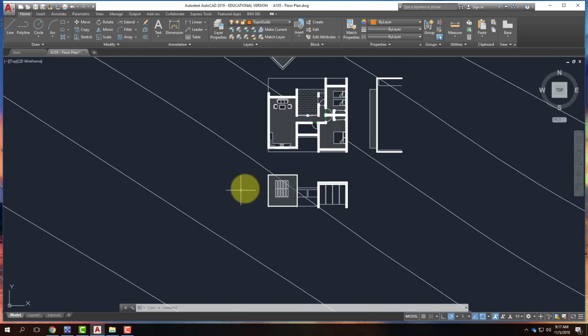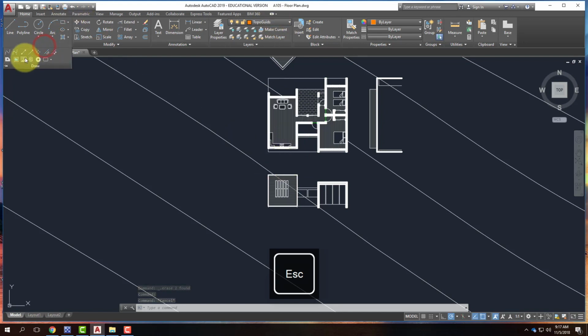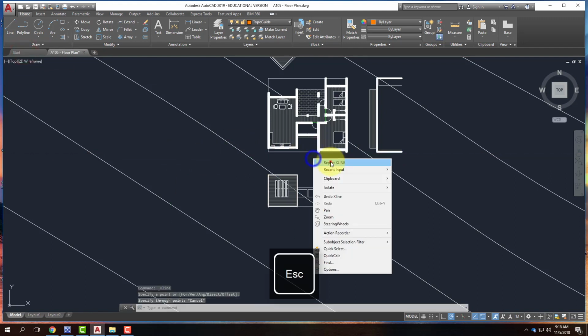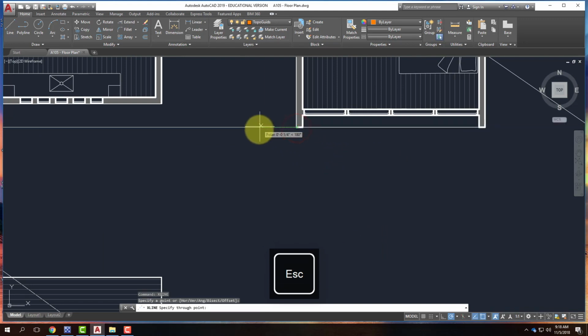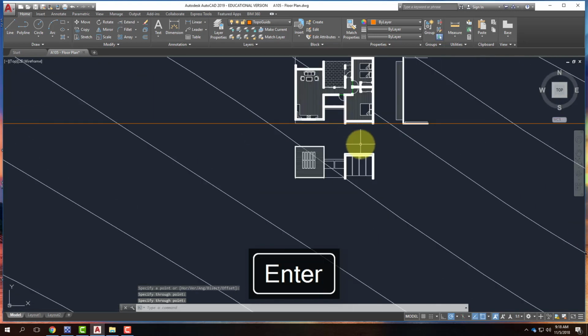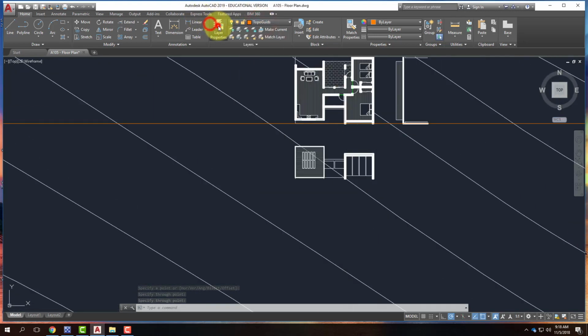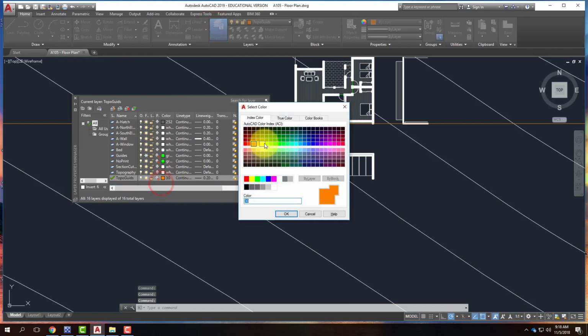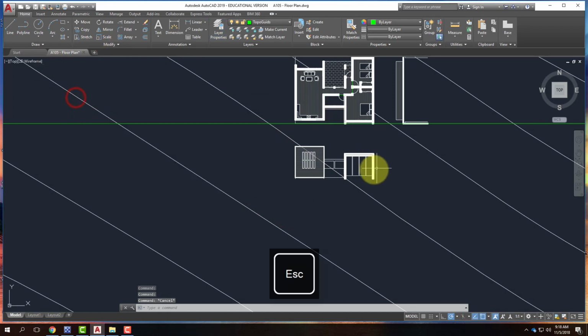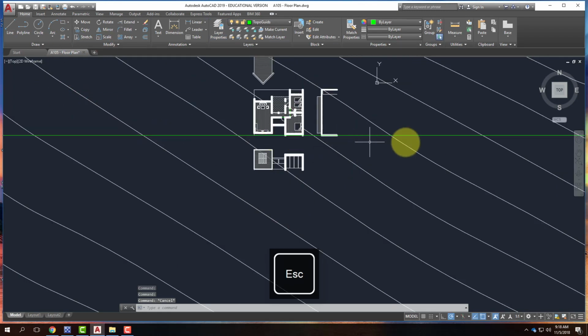So as I said, the elevation is taken on a plane that is right in line with this face of the building. So with the Topo Guides layer on, I'm going to do a construction line, an X line, that goes right along the face of the building, right? It would help if I could snap to the building. There we go. That goes right along there. Yeah, you can't really see it. Let me change the Topo Guides color. Like I said, I was avoiding green, but it looks like green is the only one you guys can see, so that's what you get. Okay, so that's right along the face of the building.